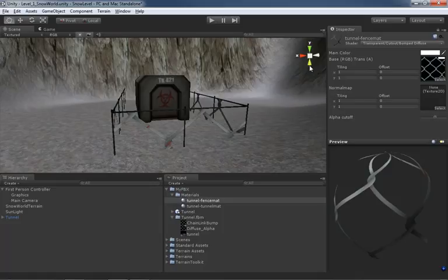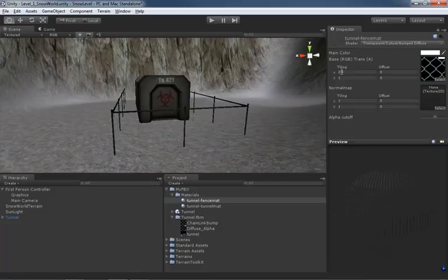Now, let's go ahead and set up our tiling. It's going to be here in the inspector in this tiling column for X and Y. Now, X and Y are analogous to U and V, respectively. So X is U, Y is V. Just keep that in mind. And what we had set up, I believe, was 25 in U. So let's do 25 in X. And then 20 in V, which will be 20 in Y. So let's put in 20 and press enter.